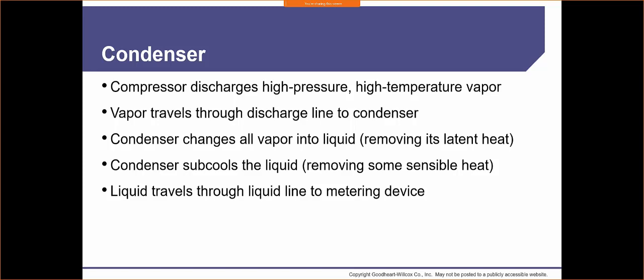By knowing my superheat, I know that as the refrigerant flows through the evaporator, as long as I have 10 degrees of superheat, I'm not going to get liquid forming before it goes into the compressor. So when we charge our systems, we want to make sure that we have a superheat.